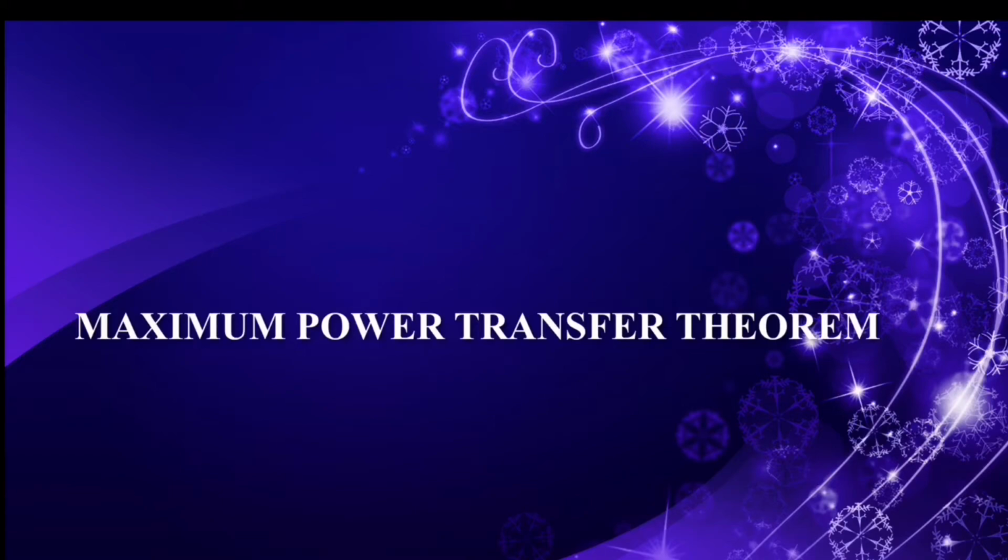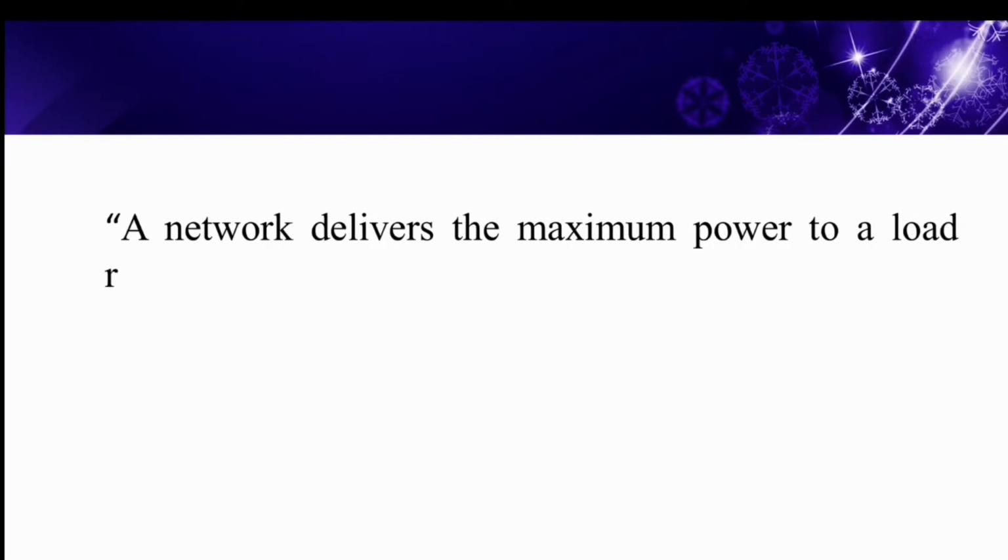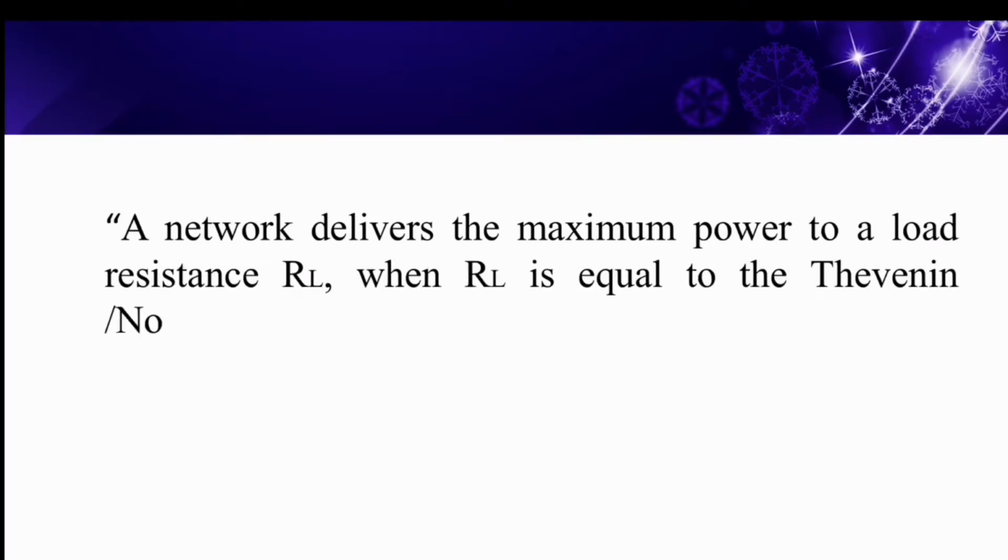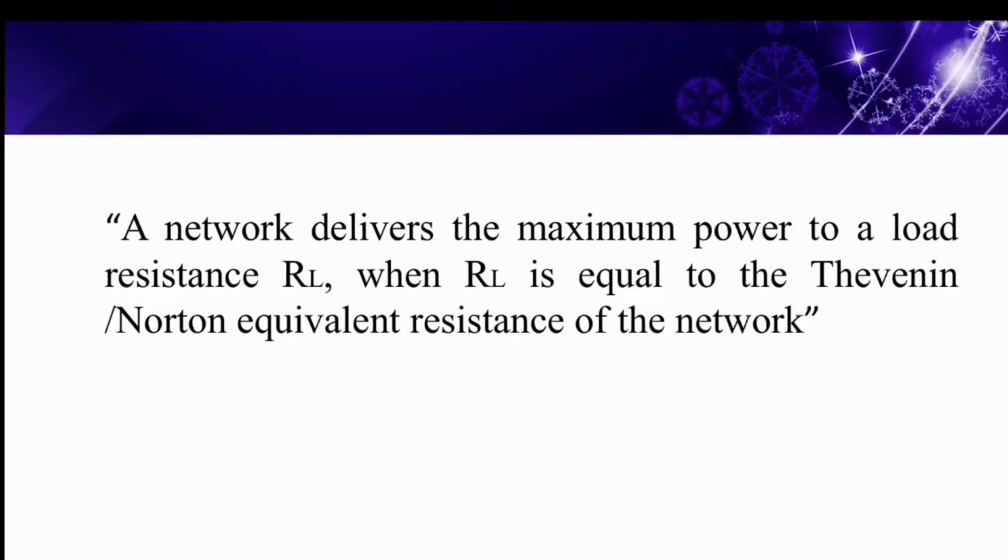In fact, maximum power transfer theorem tells us about the condition at which maximum power transfer can take place. It says a network delivers the maximum power to a load resistance RL when RL is equal to the Thevenin or Norton equivalent resistance of the network. Got it?